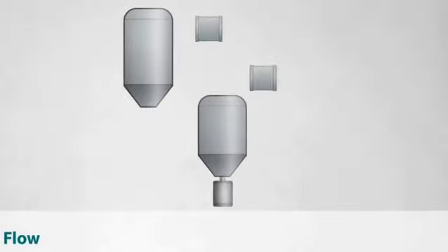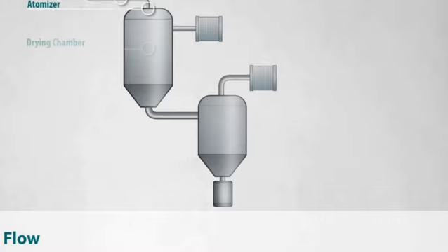The next stage is atomization. The prepared liquid is broken into extremely fine droplets. This can be done using either a nozzle atomizer, which sprays liquid under high pressure like a fine mist, or a rotary atomizer, which spins the liquid on a disc to fling droplets outward, like tiny fireworks.